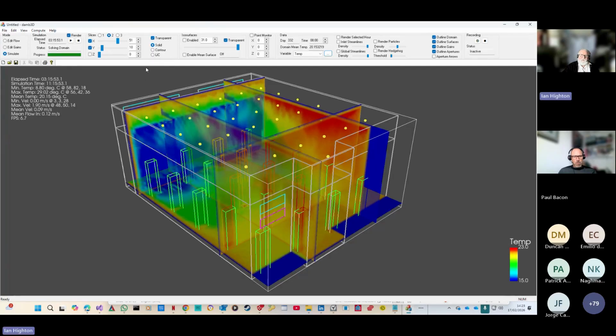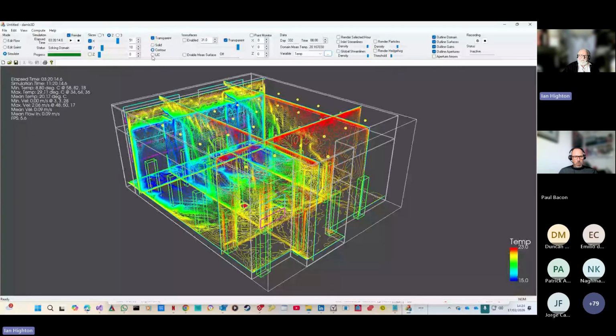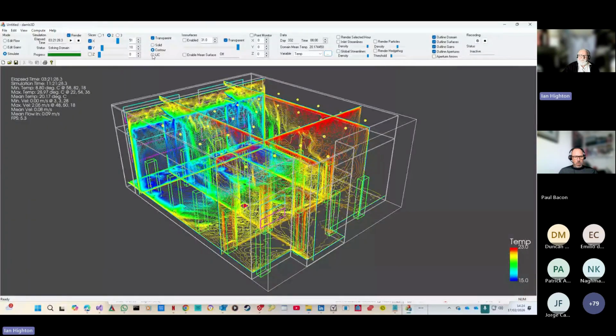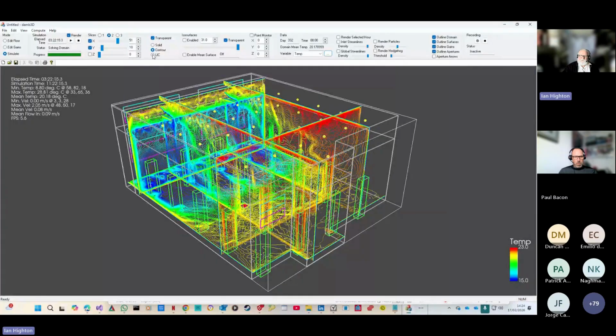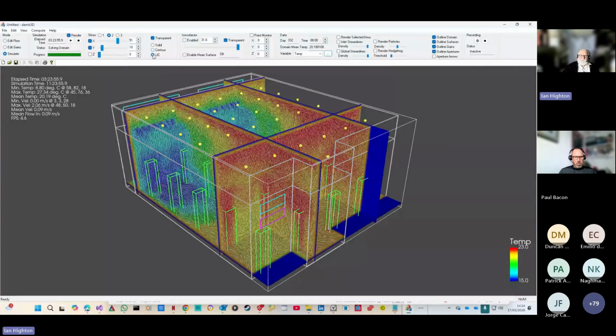Yeah, and there's some other display options. So you can look at contours, which is a bit leery. There's also line integral convolution. I'm less convinced that this is actually a useful feature, and it takes an awful lot of time to compute. There you go. Always looks like Van Gogh to me. But the idea is that you've got colors to represent the temperature, and the little wiggly bits are basically showing you the local airflow pattern.